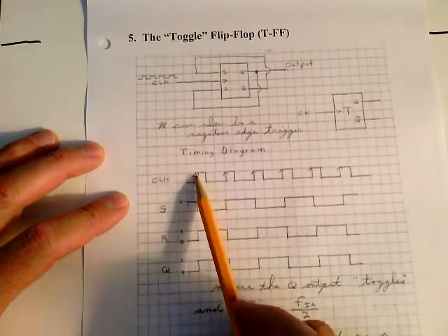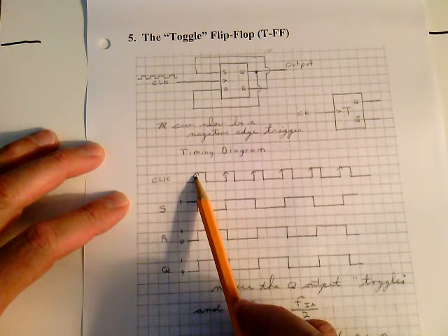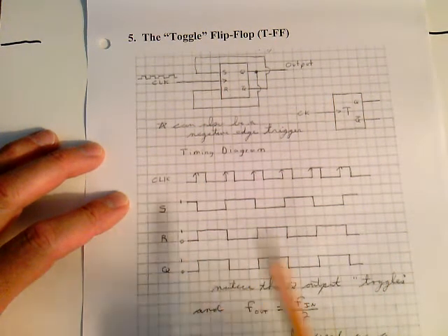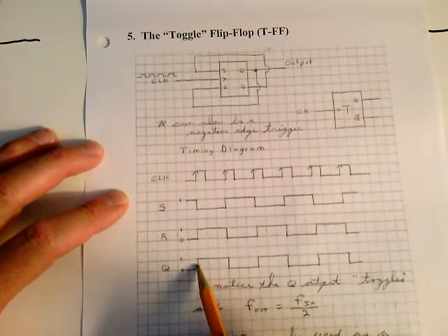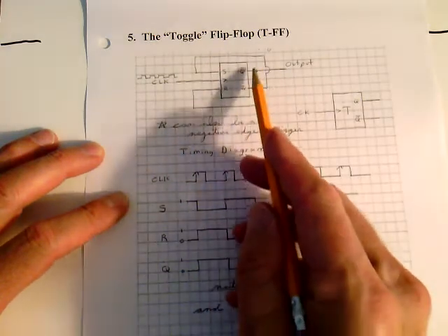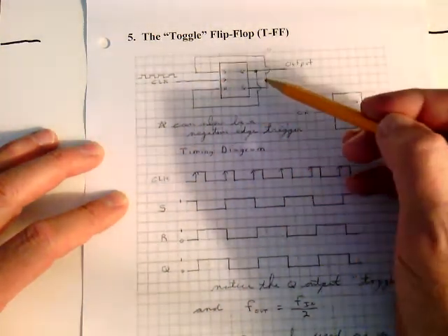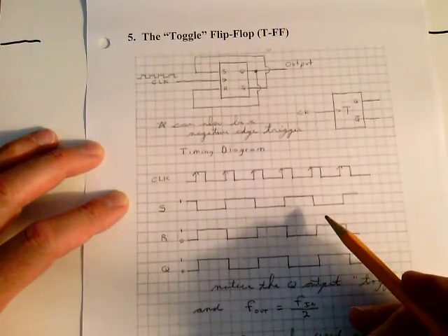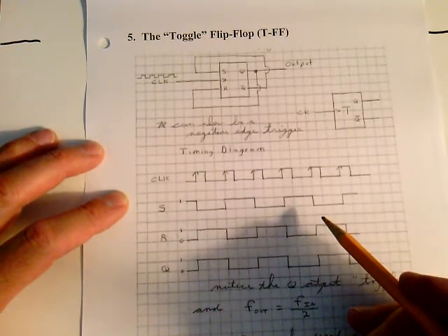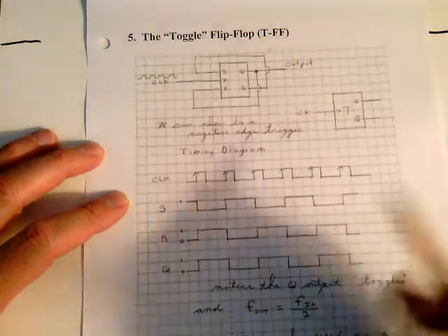When the clock edge comes, notice what you're going to do to the output. The output is going to go high. It's going to set. And you can go through the 1s and the 0s each, and feed, and this gets set to a 1, and this is a 0, feed them around, wait to the next clock. And when you see the next clock, the Q output is going to get reset.